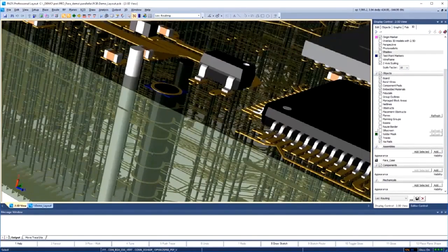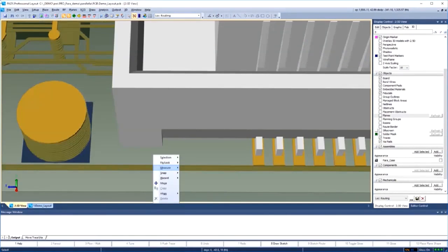Measuring is a simple right mouse button click away, making it easy to quickly measure between objects in order to check against potential clearance and assembly issues. Double-check connector placement in regards to the assembly and component offset from the board edge. By simply clicking once on the object of interest, the measurement tool automatically snaps to other objects when moving the cursor. Remember, you're checking the design before the PCB is sent out for prototyping, allowing for extra passes of verification.